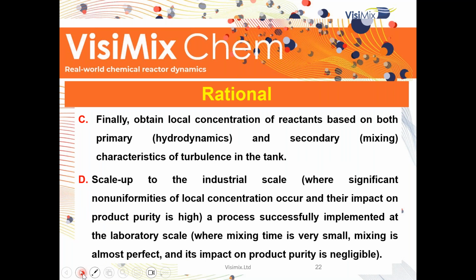After that, because we feed materials, we get the local concentration of reactant based on the hydrodynamics and micro mixing. And once we have it, we will be able to compare these conversions and results in the different equipment in the industry, because once we know that the reaction is always the same, we don't have to take care of where it happened. The chemical reaction is not a function of the equipment, but the environment we're providing to the reaction can be different and can generate deviation in the results. And this is the point where we can, of course, go to scale up, industrial scale, and generate good results.